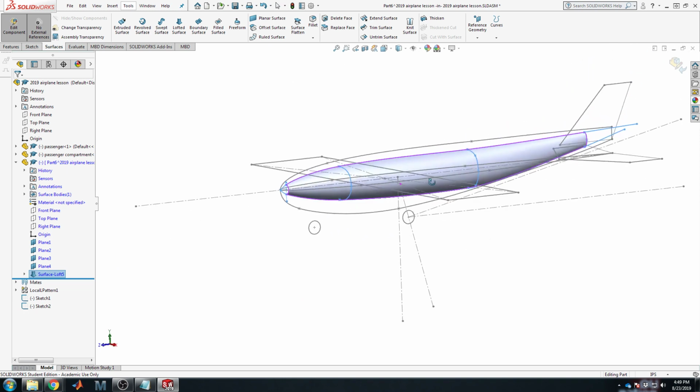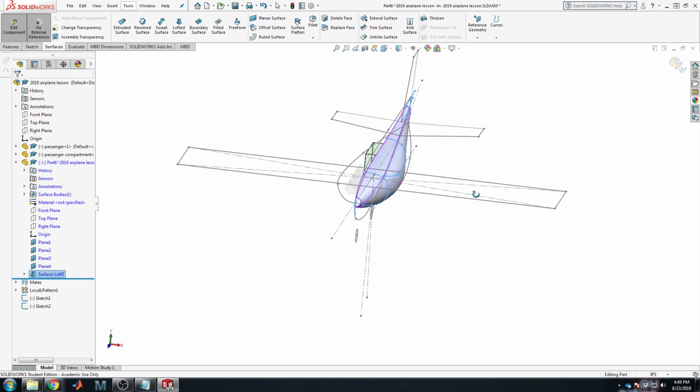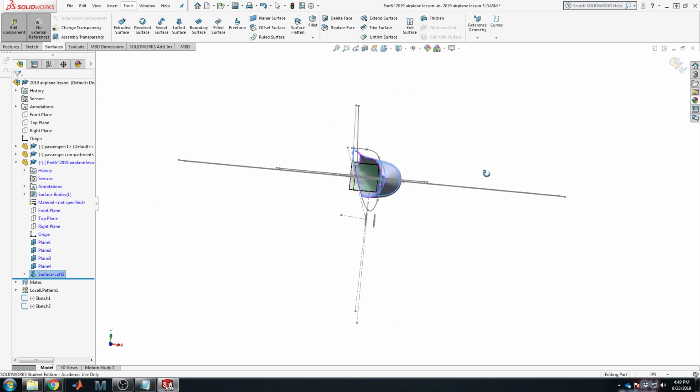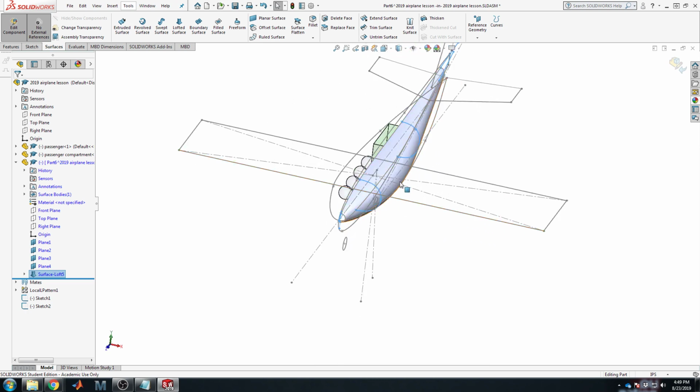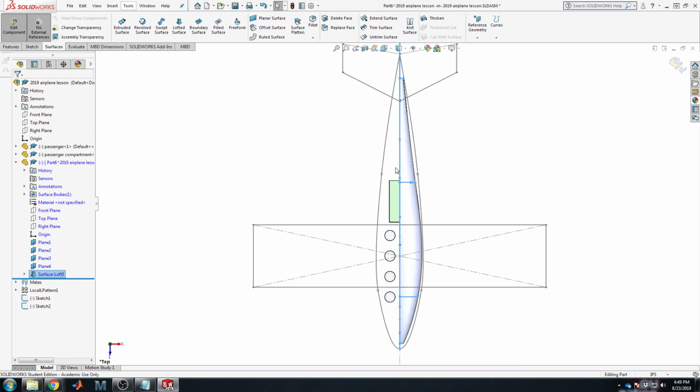You can also set these up with three-dimensional sketches, which gets a little bit crazy, because right now the thing I'm seeing is that right here around the third or fourth row of passengers, it's getting a bit wide. Right? I mean, aerodynamically, that's pretty good. I mean, it's very smooth. It evolves nicely, but still, you could squeeze a little bit of fuselage fatness out right there, and that might decrease your total width of the fuselage, decrease drag. It might make it worse. Who knows? Do some studies.